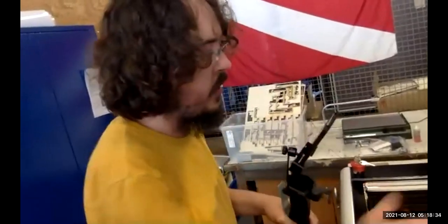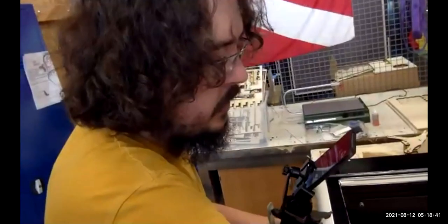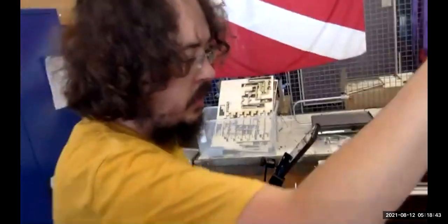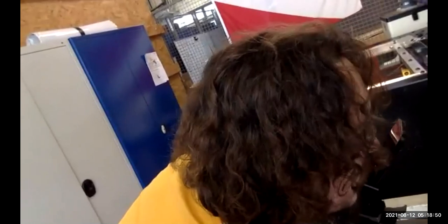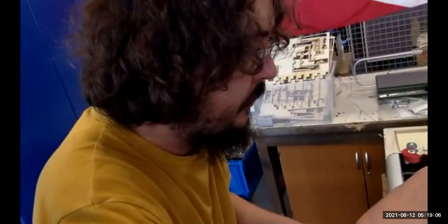For holding the piece, you can position it by hand. Just move the head wherever you want, for example, and you have it here. Or you move the piece wherever you want. Then we close the machine. We go here and open the G-code, which is this one, a very simple circle. We reset the 0 for the positioning, and then we're ready to cut. 3, 2, 1, play. And guys, now we are cutting 10 millimeter acrylic.